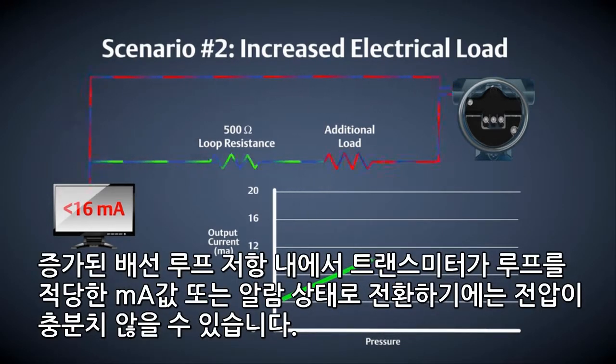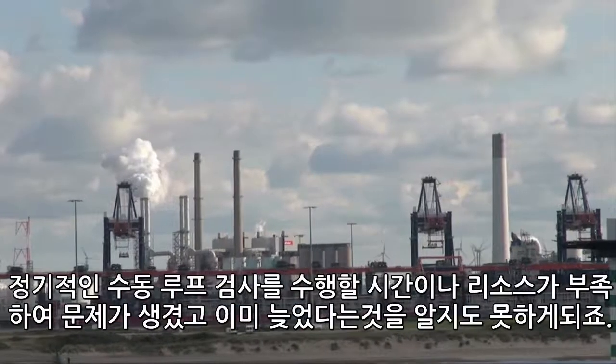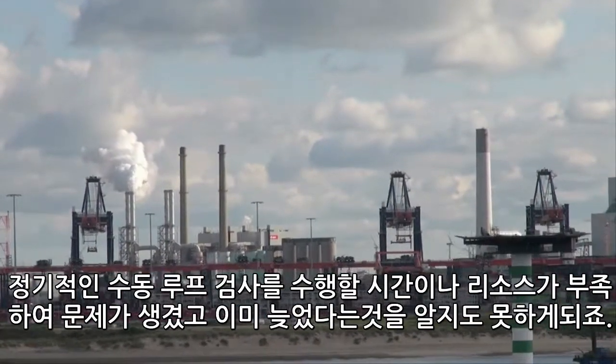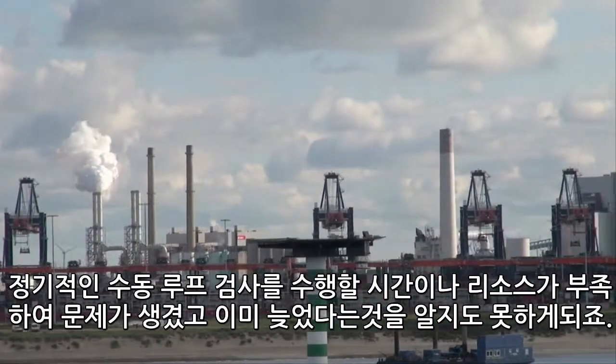With an increased wiring loop resistance, there may not be enough voltage for the transmitter to drive the loop to the proper milliamp value or even to an alarm state. In this example, the transmitter is unable to go above 16 milliamp. You don't have the time or resources to perform regular manual loop checks, so you won't know that there is an issue until it's too late.